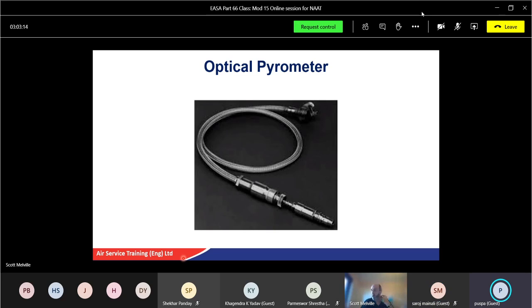Yeah, the different resistance, although they have the same components, the same harnesses, the same thermocouples, some will be older, some will be newer. Materials wear down, resistance balance. So the trim resistor, the key word is calibrates for the variances in resistance of each of those components. Okay. Averaging. We might have two thermocouples, two different lengths, and that gives us an average.